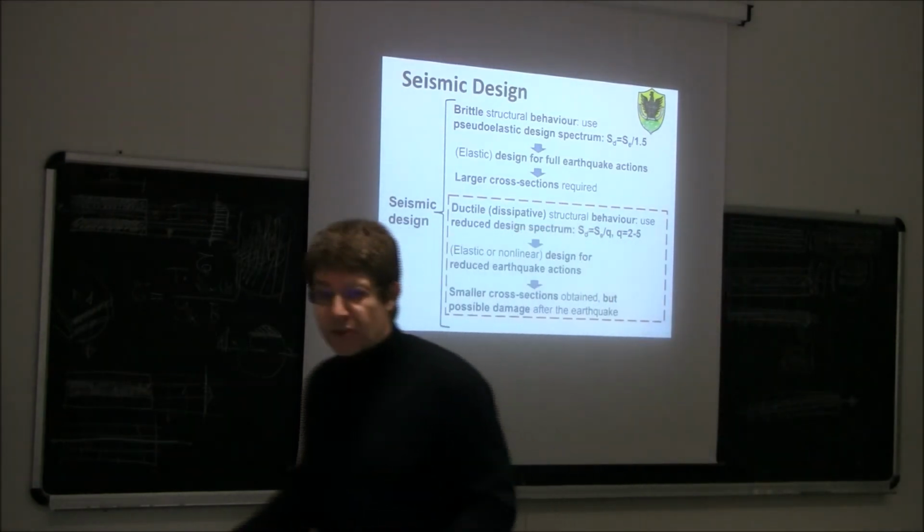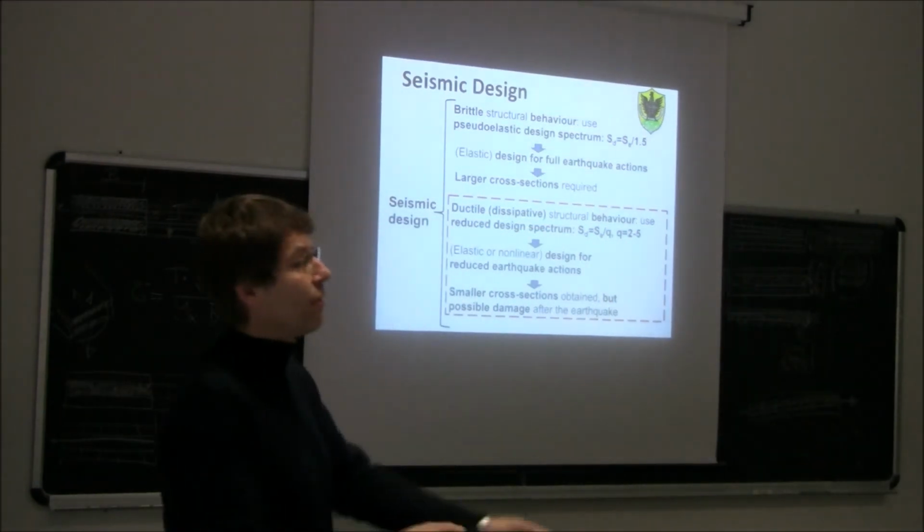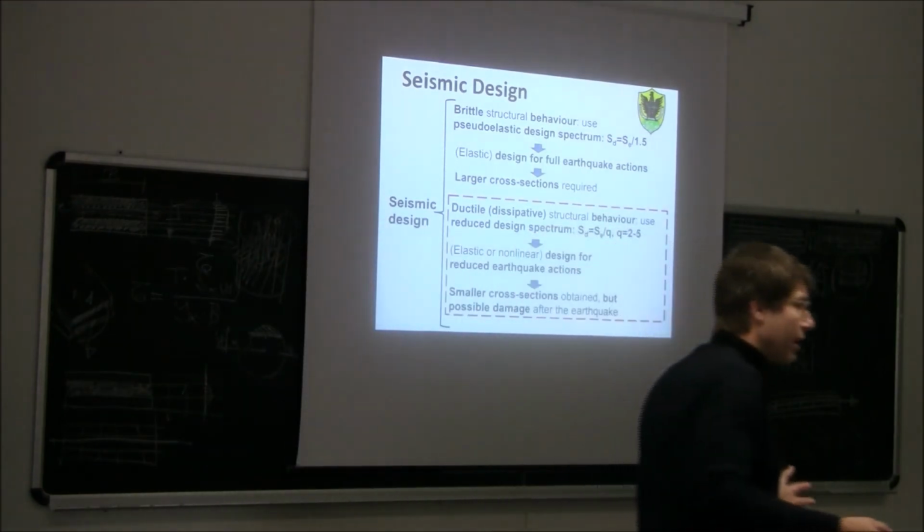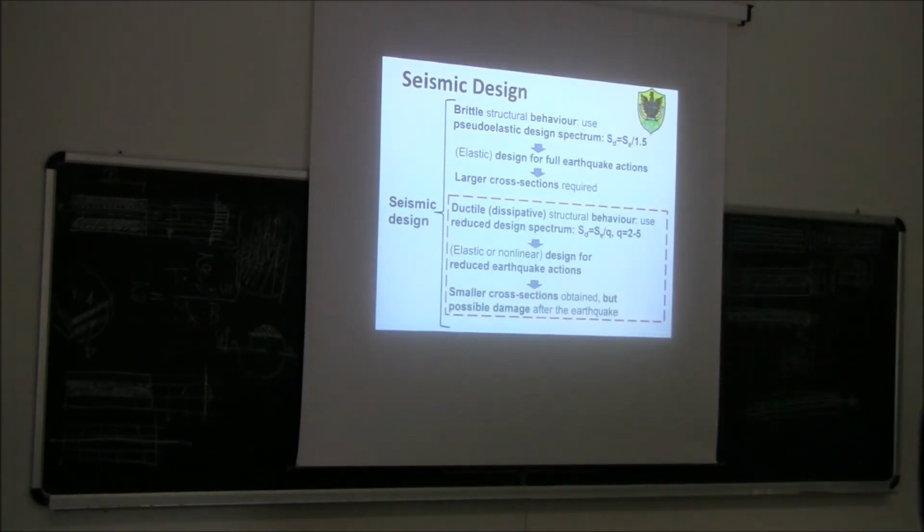Take into consideration that in timber we don't have steel rebars. However, in timber we have some steel members, right? Which steel member do we have in the timber structure? The joints, or more than the joints, I would say the fasteners. So in the joint region we have some fasteners, which are usually made of steel.